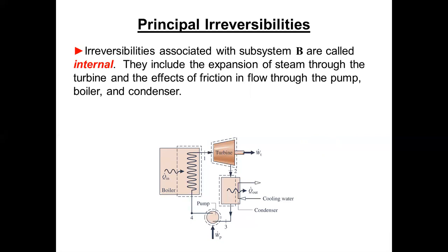And I would encourage you to do that and just look at the pressure drop. Seems like we had someplace in the neighborhood of 40, maybe 45 pounds of drop on the reheater as that steam comes out of the high pressure turbine and goes back for temperature increase in the reheater sections of the boiler, and then goes back to the intermediate pressure turbine.